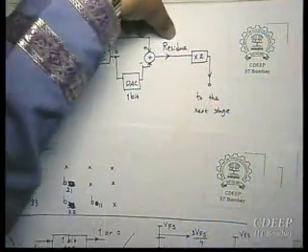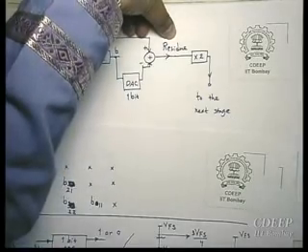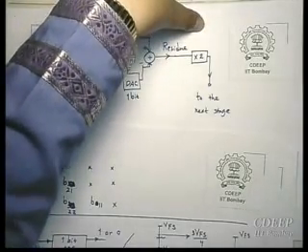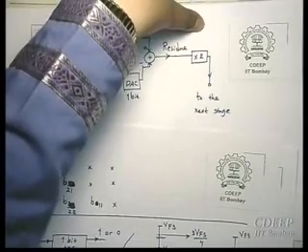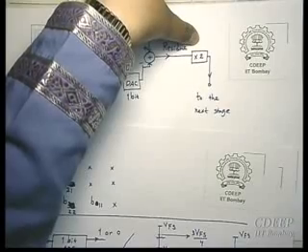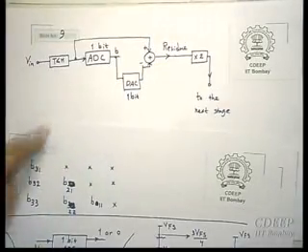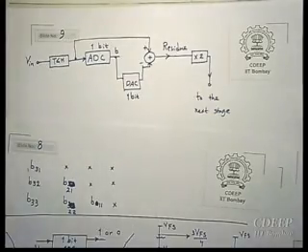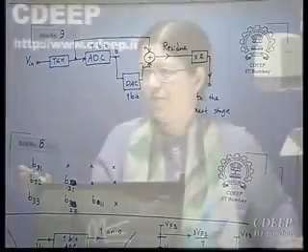The problem is with the errors. And why is the problem with errors? See, if this residue has some error, it will get multiplied by 2, or it will get multiplied by 4, or whatever number of bits you have will determine. It means that if you have an error in one stage, it will get scaled up and go to the next stage. And therefore, it will get accumulated.